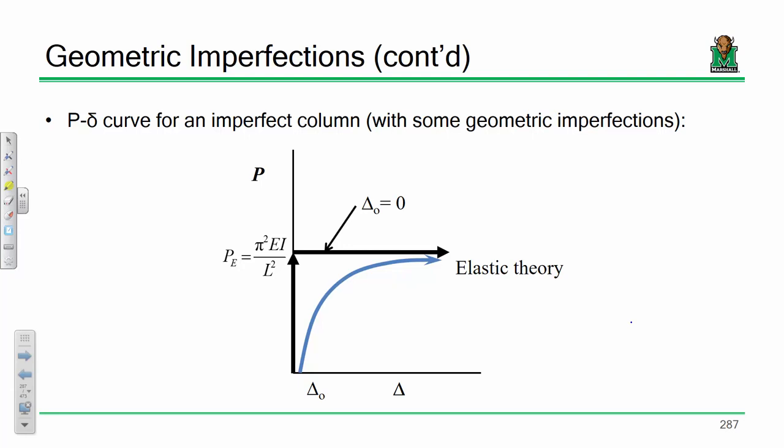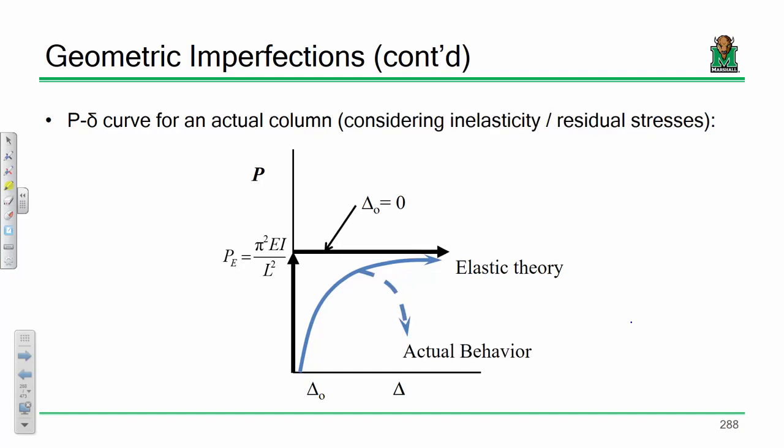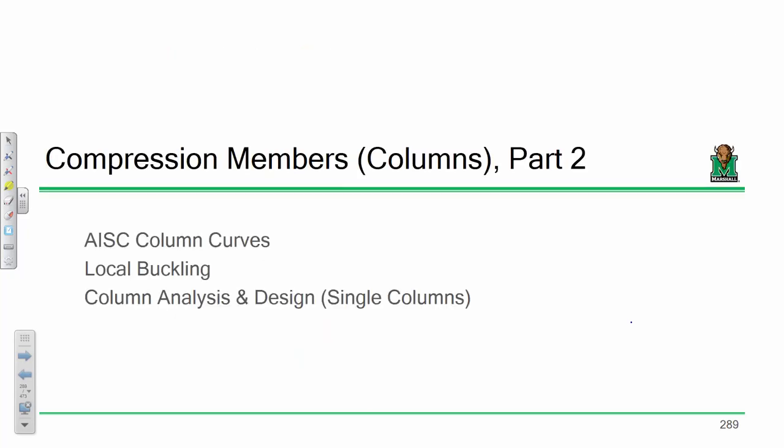And that is particularly pernicious when you have an element that's subjected to compression, because the more compression and the more moment means the weaker it's going to be. It's sort of like that whoa, whoa, whoa feeling, because it sort of builds on itself. Well, that's what happens with columns if you have that second order effect. And if you take that second order effect and combine it with residual stresses, you can have some pretty significant reductions. So the question that Ashton asks is, well, how do you account for all this?